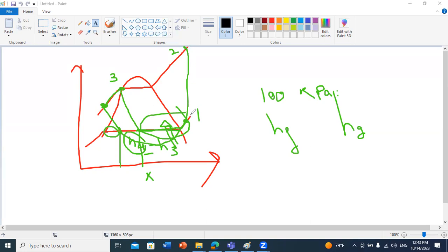In this example, at the outlet of your compressor, you have superheated state. And once you enter the condenser, you will go first from superheated state to saturated vapor, and then the condensing process will continue. It can continue until point 3 or can continue furthermore.